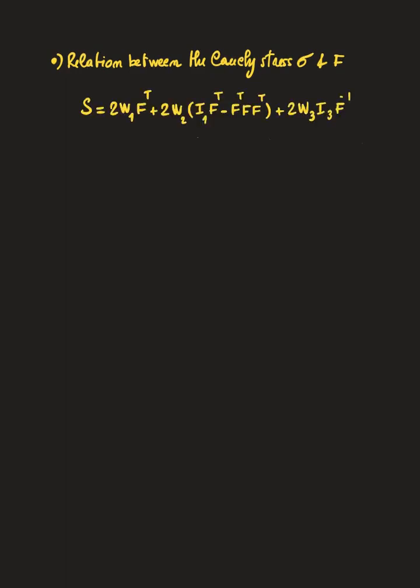First, I copied the expression of the Piola-Kirchhoff stress we obtained in the previous slide, and all I need to do to deduce the Cauchy stress is to remind you that the relation between S and sigma is S equal to J F minus 1 sigma, where J is the determinant of F, usually denoted in this way. So from this expression, if I invert it...